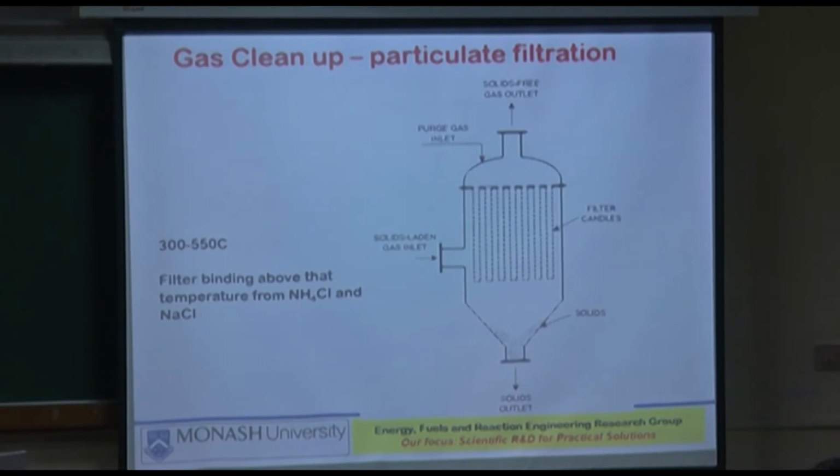If you put in too much purge gas, it will disturb the hydrodynamics inside the cyclone. It can give a pressure drop in the opposite direction, and a whole lot of problems can happen. If you do it too low and too infrequently, then there will be ash bridging. It also affects the quality of the syngas for that period.